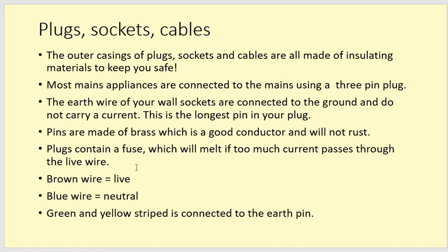Plugs, if you can open them up, have a fuse. It's about 1 centimetre long. It's a little cylinder piece. You have to match the fuse to the appliance. They are a safety feature, because if too much current passes through it, the fuse will actually melt. People describe that as being blown. When that happens, the current will stop flowing and you are protected. Most plug appliances these days have molded on plugs, but you can still have a little space where you can pop a fuse in and out.